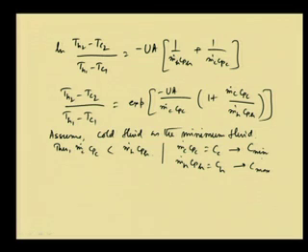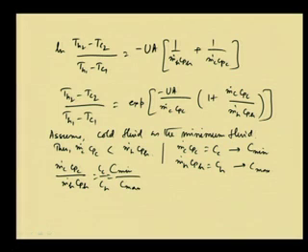Therefore, m dot c Cpc by m dot h Cph equals Cc by Ch equals C min by C max. In the present case we have assumed cold fluid as the minimum, and this we write as Cr, the heat capacity ratio.